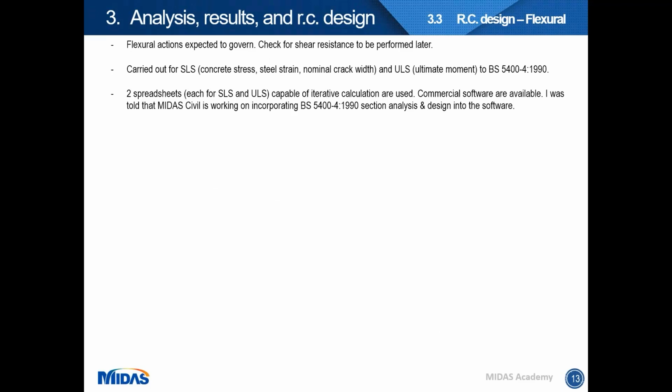So let's say we have all our bending moments, shears, and reactions. We proceed to doing our reinforced concrete design. For this solid slab bridge, I expected the bending moment to be governing over shear. So that is why I designed the slab first against the bending moments, then I checked against the shear resistance. The flexural sectional design was carried out for both SLS and ULS as usual to BS 5400.